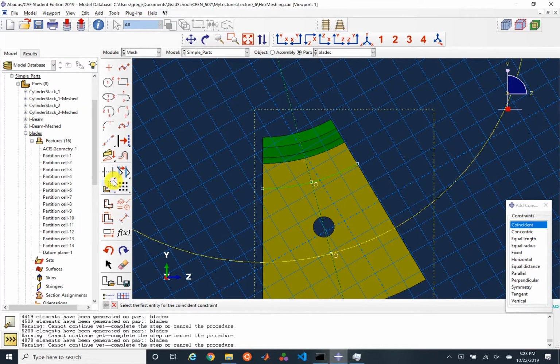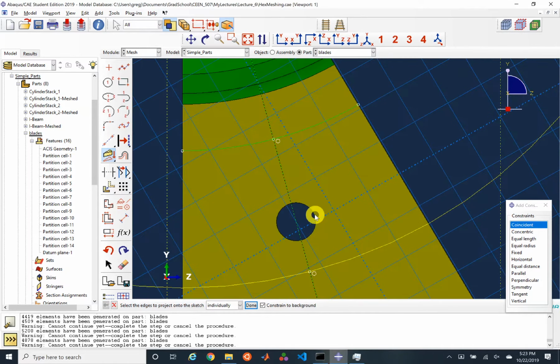And then now what I can do is I can project this circle up. Now this is maybe outside of this lecture here, but you might have thought, oh, I have a circle, I'm going to project it up, and now it's going to be another circle. But it's not actually. There's a circle in a different plane. It's now being projected up to a plane that's not parallel to itself. And so these end up being transformed into non-uniform rational B-splines.